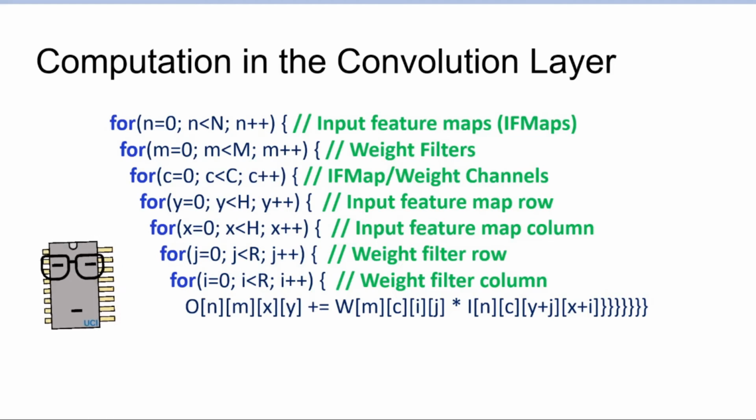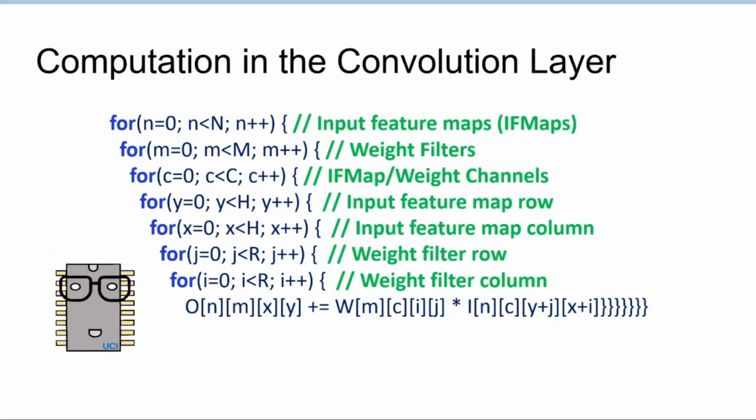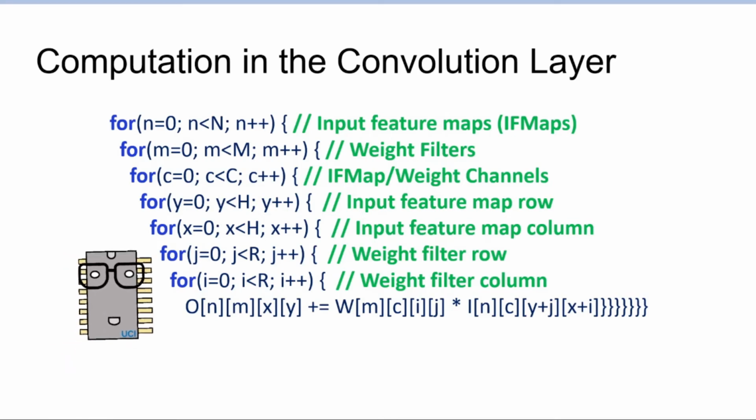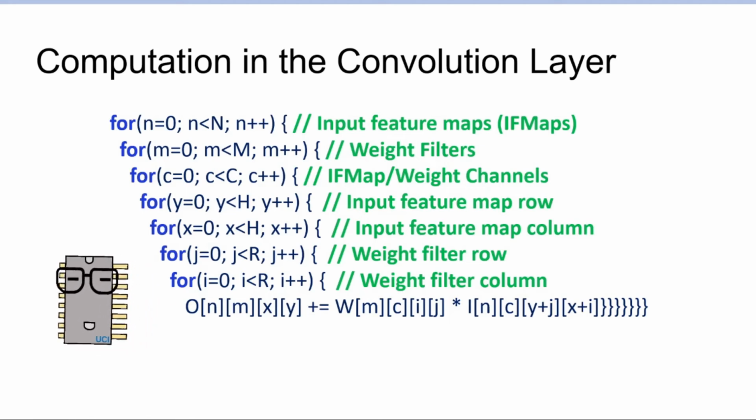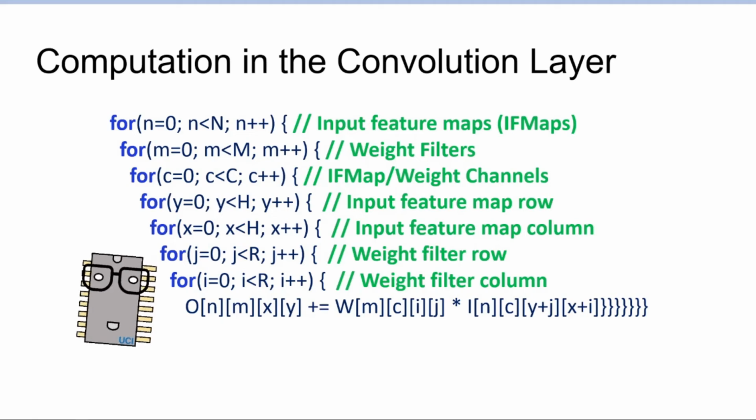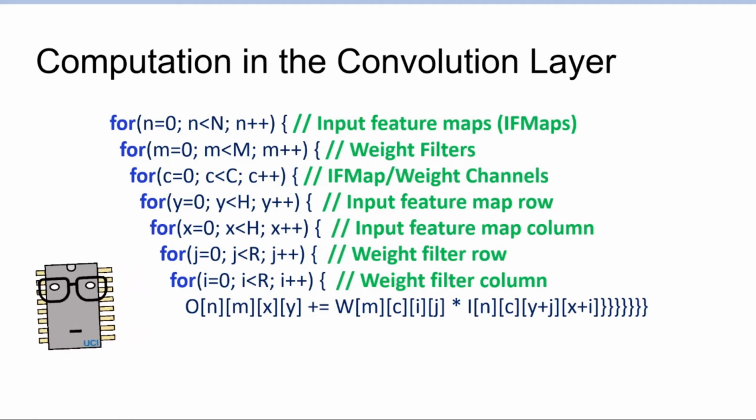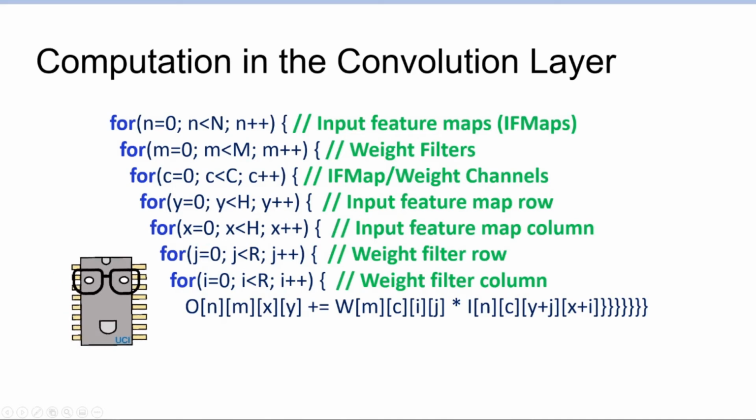And again, you can see something like a fused multiply-add, or pretty much floating point multiplication and floating point addition, is the key work being done for the convolution layer. This is pretty much the same at a high level as the fully connected layer example we were looking at, which is just matrix-matrix multiplication, almost completely consisting of floating point multiplication and then floating point addition. So you can kind of see a theme here.